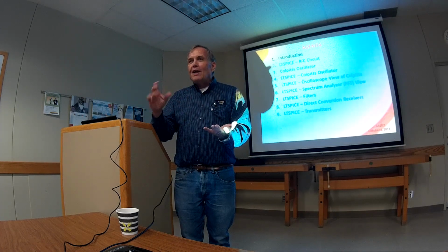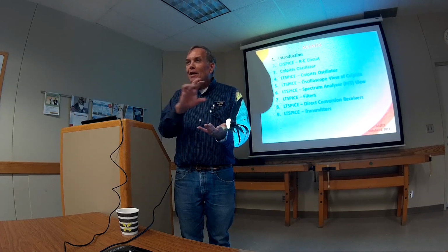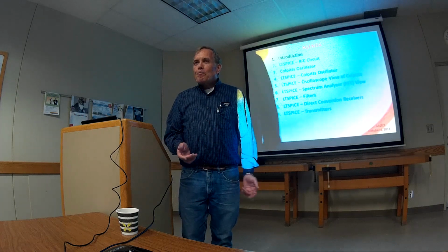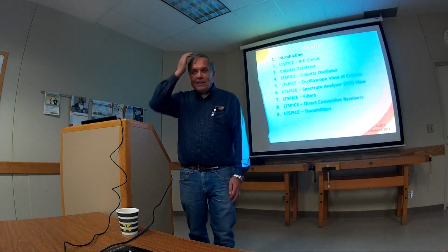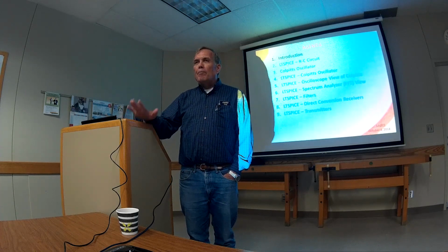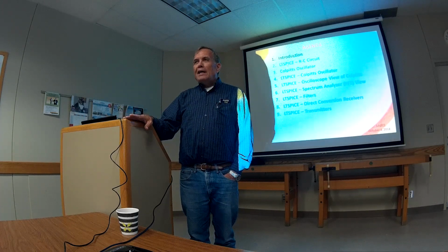Now, he said, make the model match that. Okay, so you have to add in a little stray capacitance, you have to add in a few other parts. See how close you can make the model go to the real one. And that's not as easy as you think sometimes, because LTspice is going to give you an idea, or get you in the ballpark, but it's not the real thing, okay? It's going to get you close.